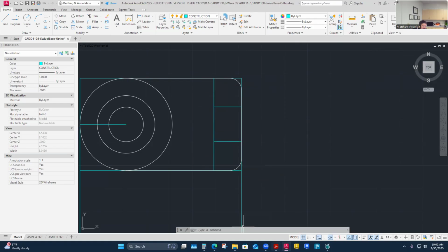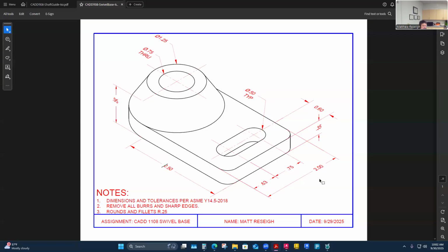When I see a dimension like that, where it's 2 3/4, I would think centered, and I would think 0.625, 0.625. This maybe should have been 3 decimal places instead of 2 if I really wanted to hit true center. I'm going to draw it to this though, because that's what I was given. So there might be a reason that it's 5 thousandths different. But it could be an inaccurate part too, if this was supposed to be held not to 2 decimal places but actually 3. So what's happened is it's affected this dimension over here. It's not centered by 5 thousandths, because that's what the dimensions say.